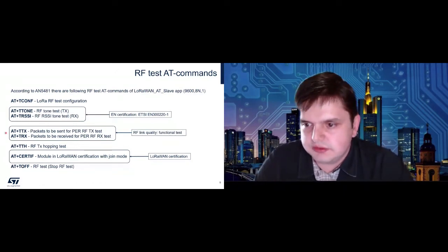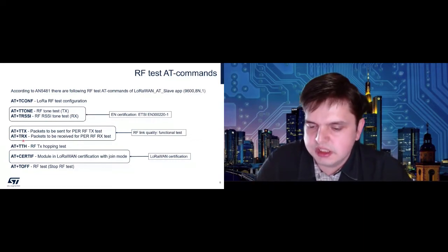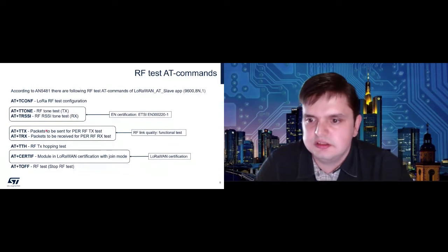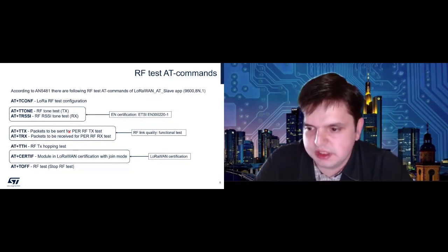Then we have AT+TTX and TRX, which is only a functional test. So one of the boards is transmitting, the other one is receiving, and the packet error rate is calculated. From the LoRaWAN standpoint, we have the AT+CERTIF.